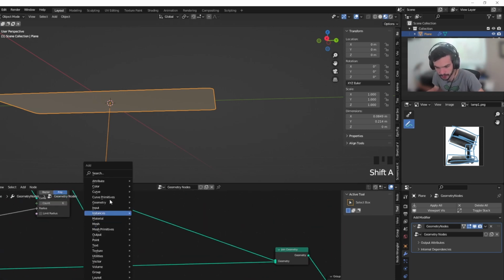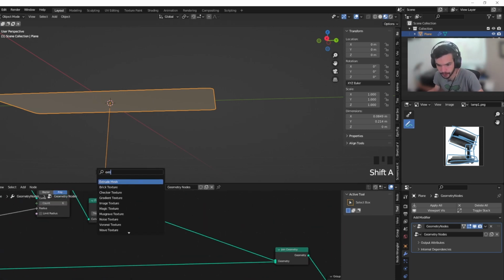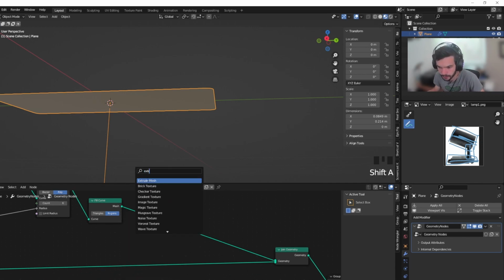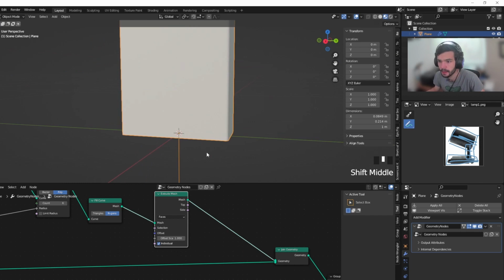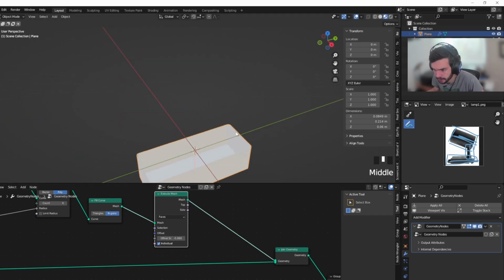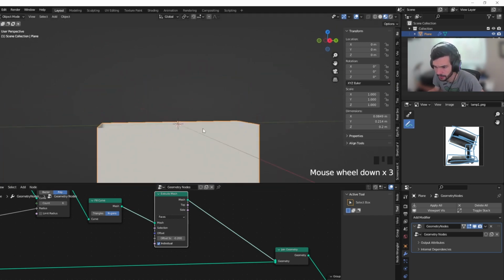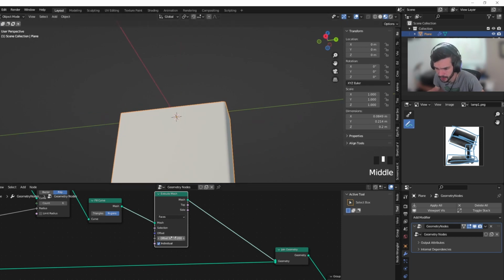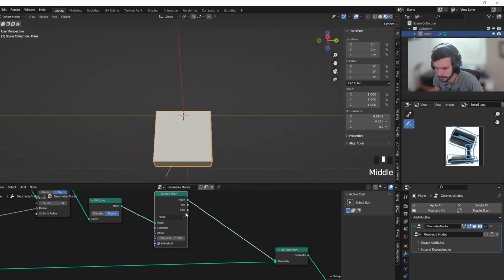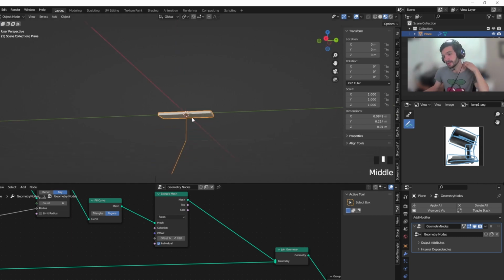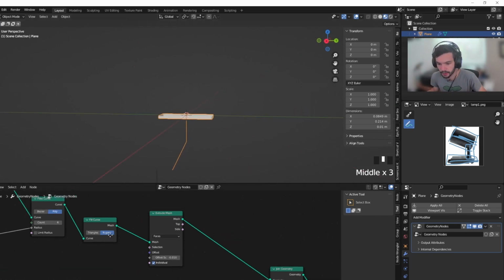Let's just extrude this. So extrude mesh. Let's extrude it in the negative direction, and as you can see, it creates this hollow box. Extrude doesn't have right now the option to close this box off, but we can go around it just by duplicating this.